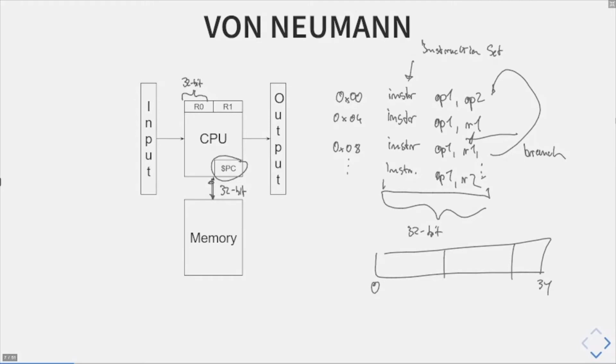We can look at this in a later slide for the RISC-V CPU, but you have a particular bit pattern that encodes, okay, this is a branch instruction, and then you can encode, for example, that you want register file 1 as 5 bits on this one. And that's the difference between those instruction set architectures, how those are encoded.